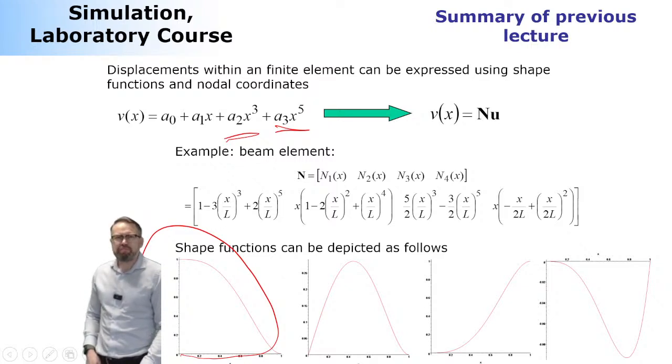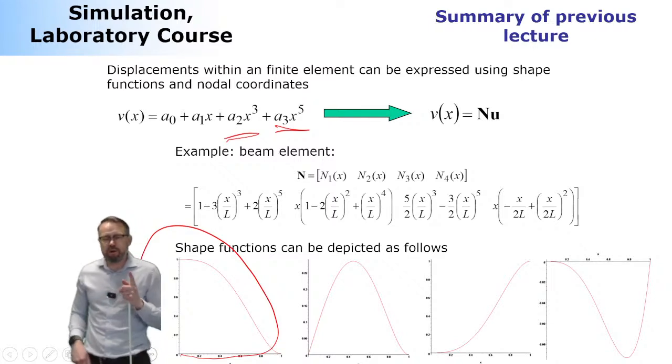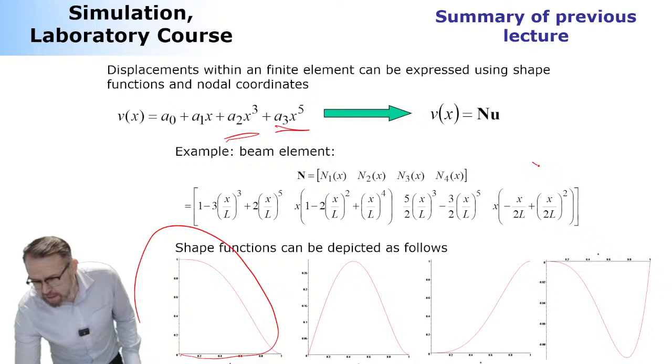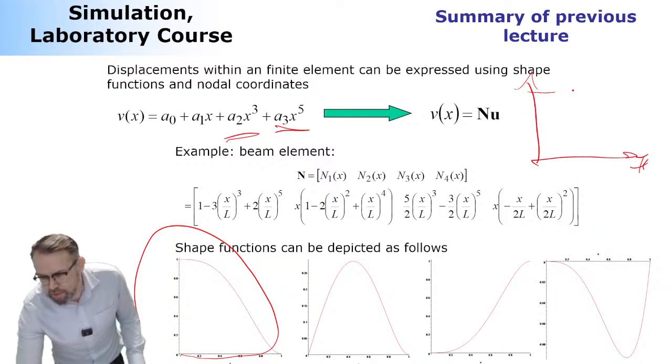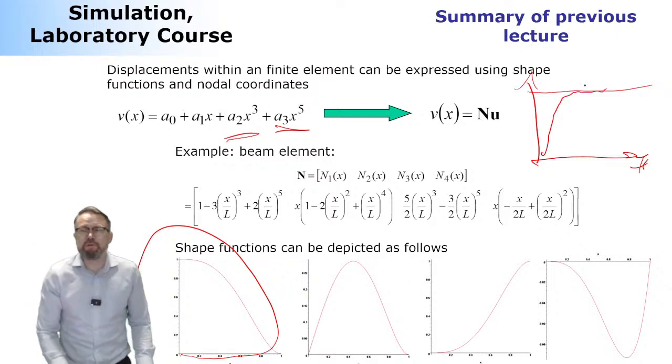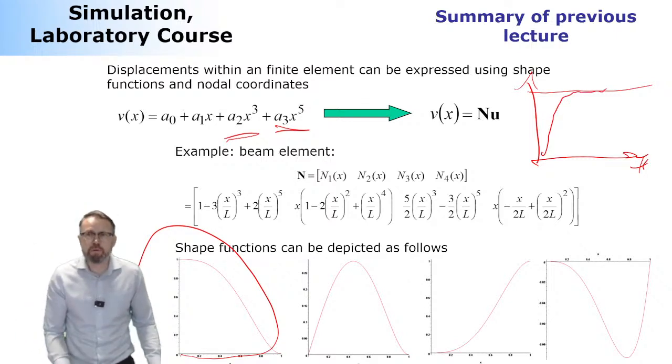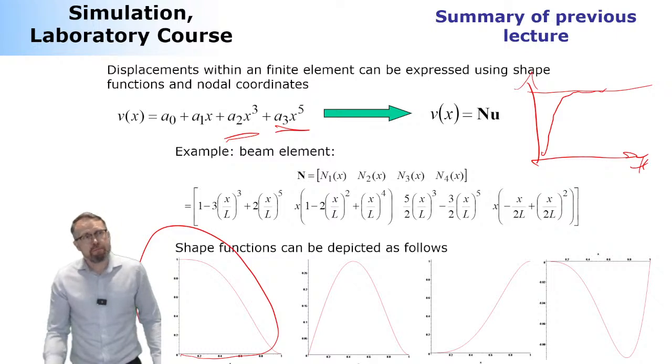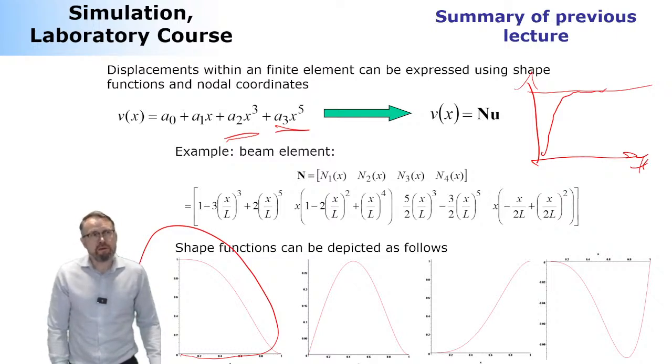Which one is better? This is a little hard to know. But as a general note, most non-conforming elements tend to have a little better convergence rate. Convergence rate was, again, how many elements you need to get an acceptable solution, how fast you reach an acceptable solution. Sometimes you can boost this efficiency by using non-conforming elements.